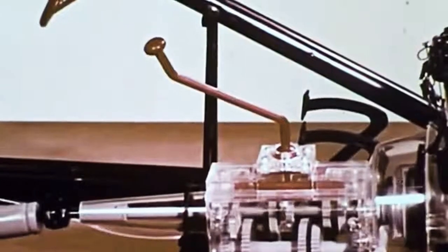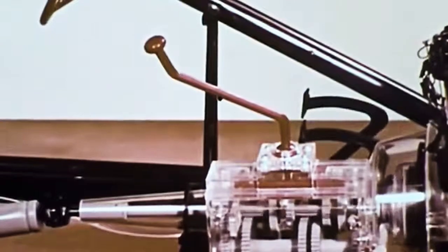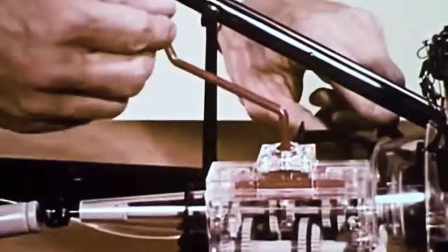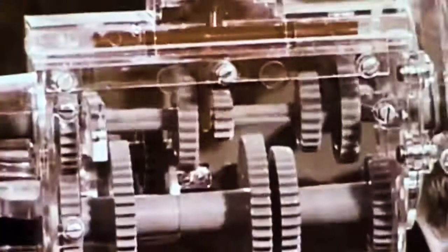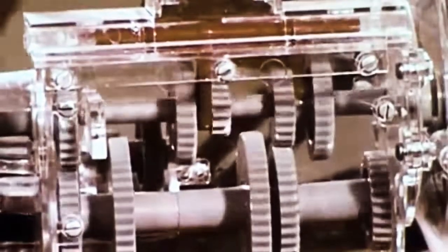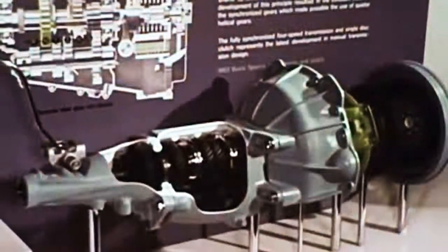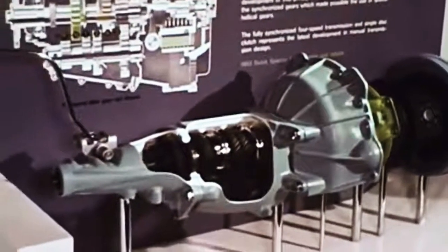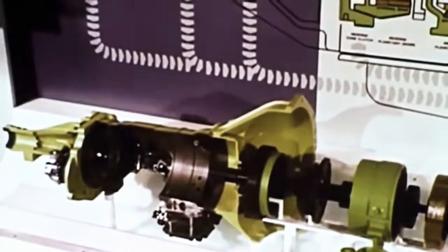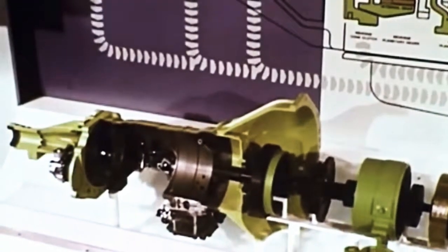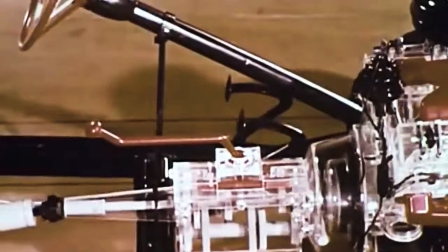Next in the powertrain is the transmission. By bringing different gear ratios into play, this car can be placed in low to start, shifted to second to accelerate, and put into high once cruising speed is reached. In most cars today, the work of both transmission and clutch is done by an automatic transmission, basically a fluid coupling and speed-sensitive shifting mechanism that simplifies driving to stepping on the gas to go and on the brake to stop.